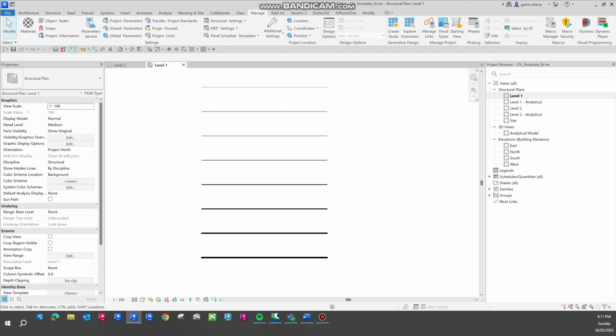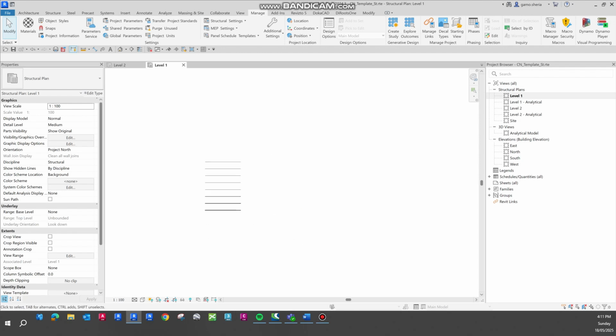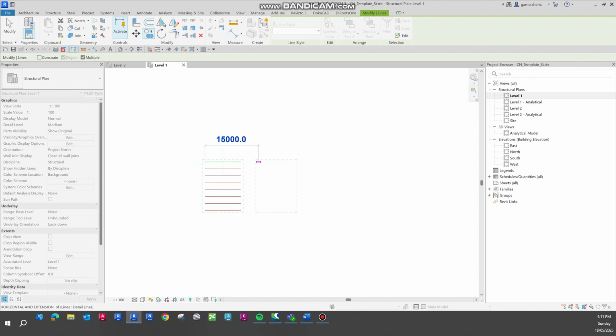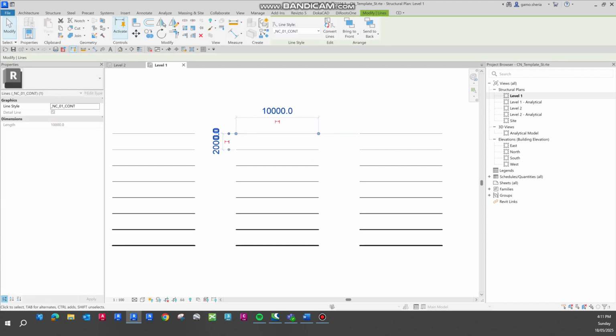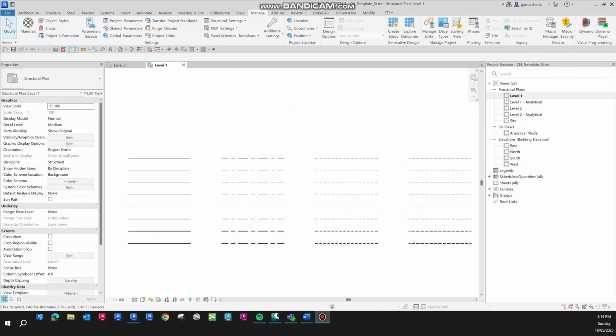So all I'm doing is making sure that these actually work according to all the settings we've done. So I need to do the other 3 types. I'll just copy this across, 50, 50, 50, and do the same thing. Just change this to center, hidden, and dashed. Right, we've done all the line styles. These are continuous, center lines, dashed lines, and hidden lines.